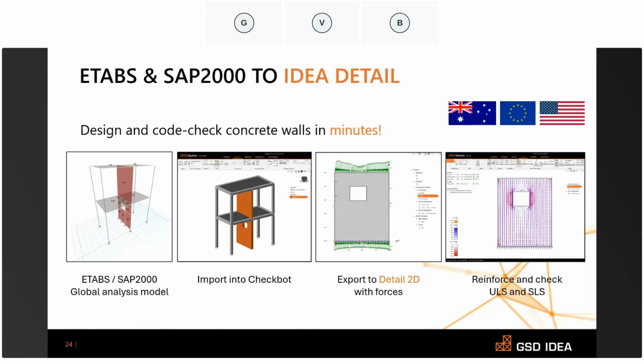Now, all that's gone with this new link. You can take your global analysis model from ETABS or SAP 2000, import it directly into Checkbot, and export it straight to Detail 2D. All the geometry, loads, and materials come across automatically. Then you can design your reinforcement, define the support, and run a full ULS and SLS check for the wall, which would also include the non-linear effects, just as I mentioned, like compression softening.